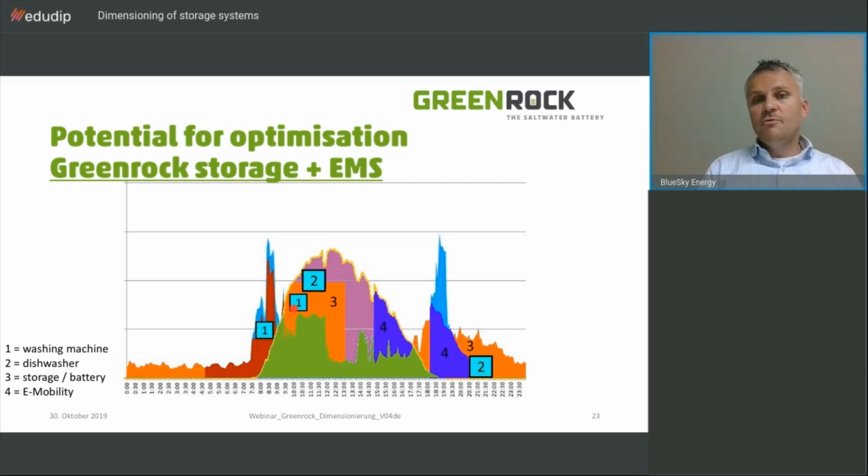What if we have got a cloudy day and we have got no excess PV at all during the day? Of course, then we can implement a certain mechanism that says, look, if we are not having energy until 1 o'clock, then smart plugs should start when there's excess PV. But if this is not the case, start ahead nevertheless, because we want to have our garments washed by the end of the day.